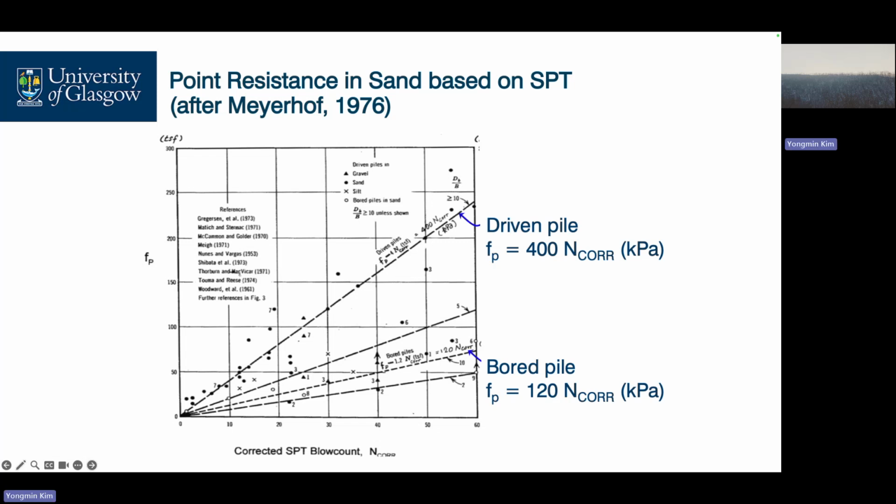It depends on workmanship. You know, bored pile means we do a pre-borehole, right? Excavate. Then we come down there and see, oh, our end bearing soil is quite clean. Then pouring concrete. We can't just excavate and pour concrete. So we couldn't check whether the end bearing is 100% clean and the circular shape is as we intended.